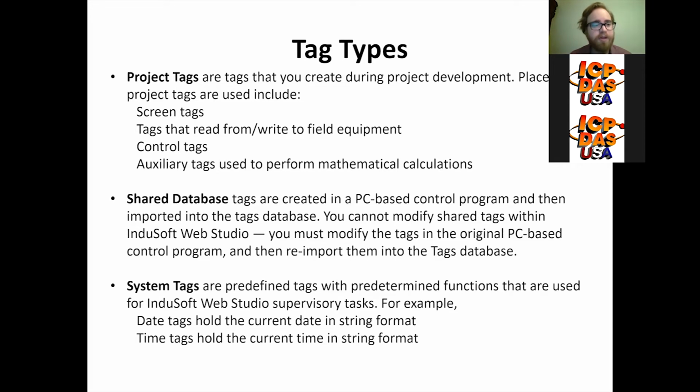But tags are more than just variables. Indusoft Web Studio includes a real-time database manager that provides a number of sophisticated functions such as timestamping of any value change, checking tag values against runtime minimum and maximum values, comparing tag values to alarming limits, and so on. A tag in Indusoft Web Studio has both a value and various properties that can be accessed, some at development and others only at runtime.